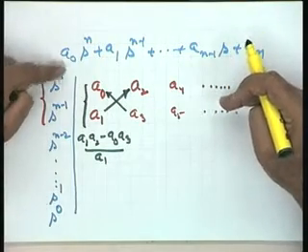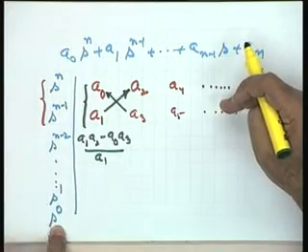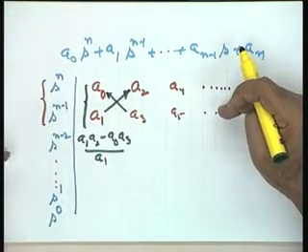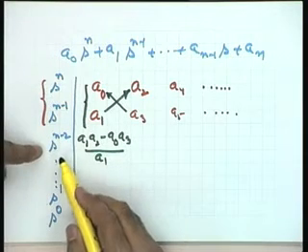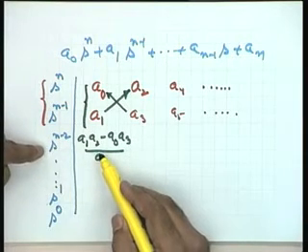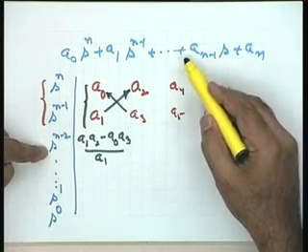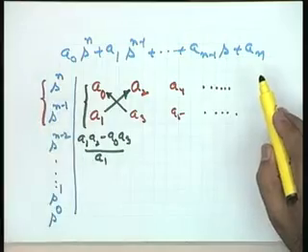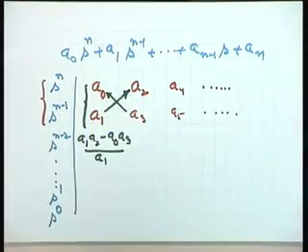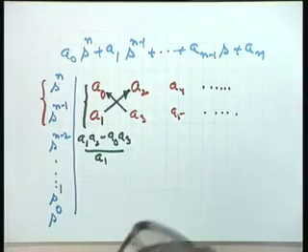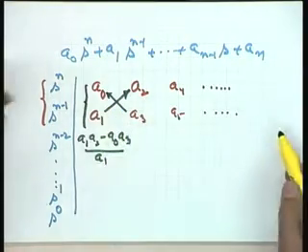If you start with n, the next is n minus 1, n minus 2 and you will go down to 0. You could write nth row, n minus 1th row, n minus 2th row, whatever index you would like to take. So, please see there should not be any confusion that the coefficient here corresponds to the term s to the power of n minus 2 in the characteristic equation. No. Once you write these two rows, the characteristic equation has lost its significance. You need not look at the characteristic equation. All other rows will be constructed looking at these two rows only.